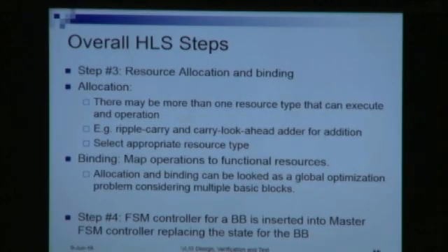Finally, the last step of high level synthesis is to build the master controller, an FSM controller for a basic block. Because I have attached timing to each of the scheduling steps, I can generate a controller that appropriately activates the functional units and, through the appropriate select inputs, the correct registers and functional unit at a given time.